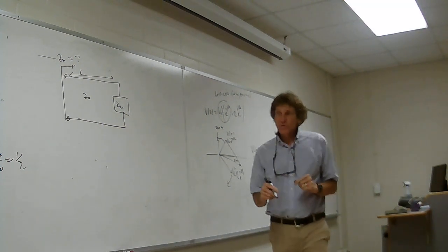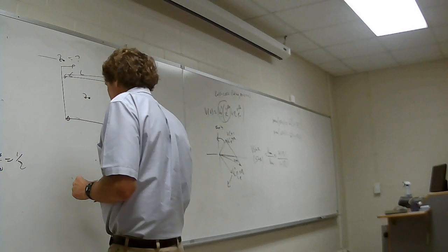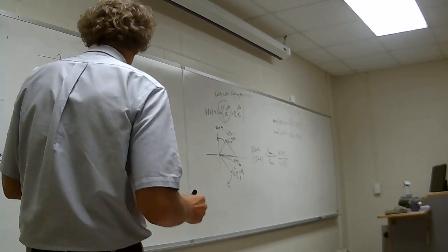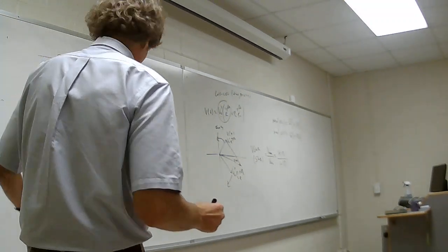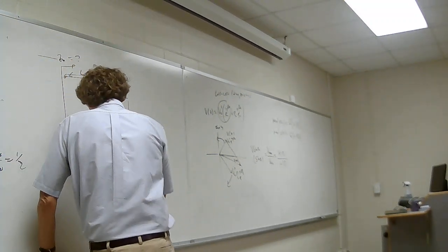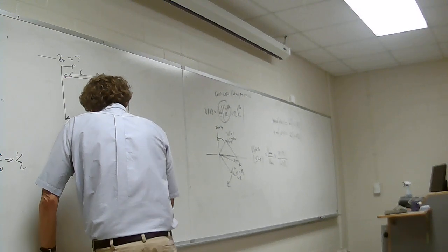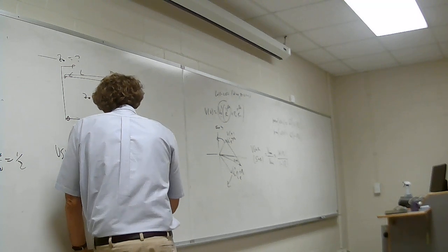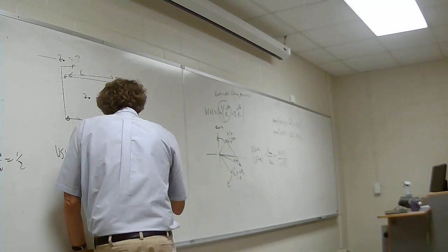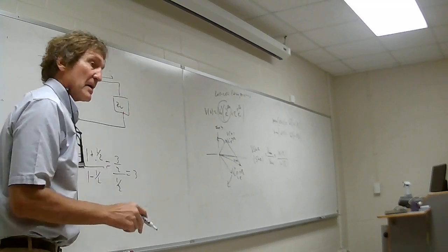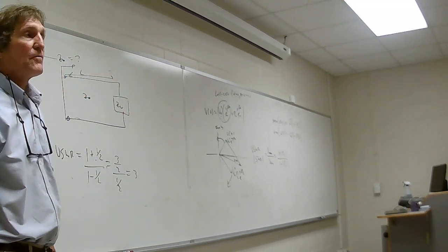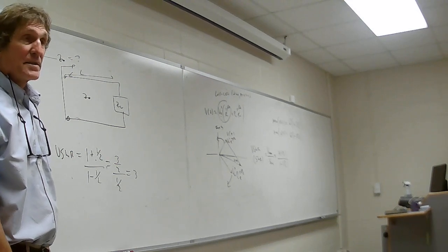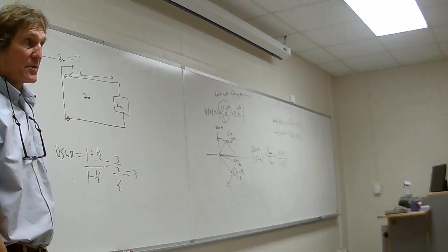Now, for this particular one, what is the voltage standing wave ratio going to be? Just take a look. What is gamma L? So it's 1 plus 1/2 over 1 minus 1/2. Remember, that's a magnitude, right? That's 3/2 over 1/2, or 3. You all see that? Yeah. That's very bad. When you get a voltage standing wave ratio anything greater than about 1.2 in a design, you're not impedance matching. That's what it's telling you.